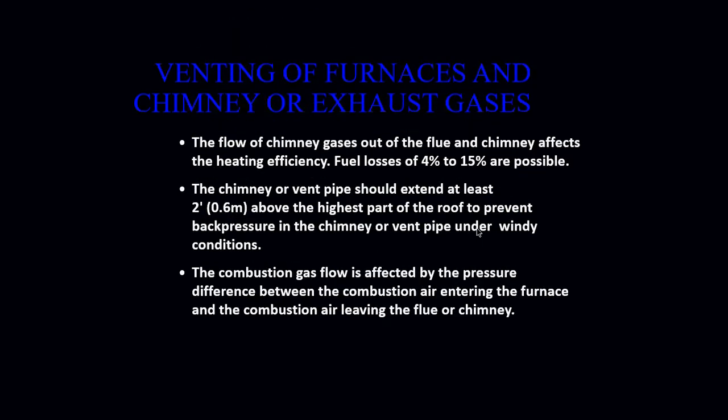Okay, the flow of chimney gas out of the flue or chimney affects the heating efficiency. Fuel losses of anywhere between 4% and 15% are possible just by simply having a messed up flue pipe. The chimney or vent pipe should extend at least 2 feet above the highest part of the roof to prevent backdraft in the chimney or vent pipe under windy conditions. If you have a messed up flue pipe and a backdraft situation, that will cause the flame inside the furnace to roll out towards you or roll out away from the furnace. We do not want that to happen.